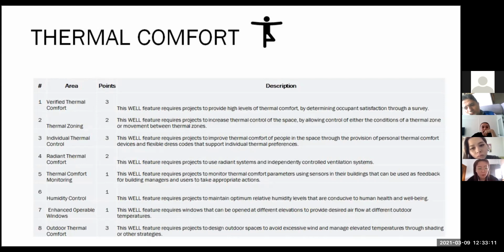And also, for example, providing thermostat control, which means temperature sensors are positioned at least 3 feet away from exterior walls, windows, and doors, direct sunlight, air supplies, diffusers, mechanical fans, and other significant sources of heat and/or cold.